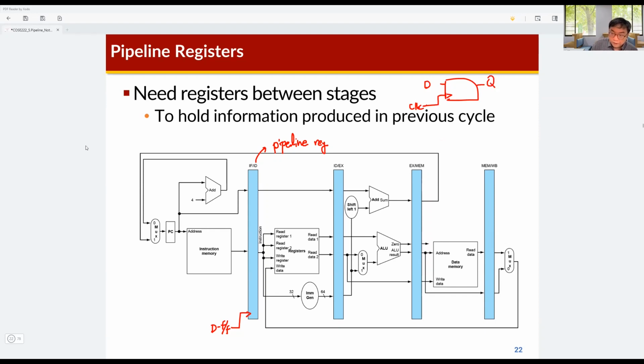At the rising edge of the clock, this input signal is sampled, and the output is maintained by this sampled value of the input signal during a single clock period. That means the input value is temporarily stored in this D flip-flop.